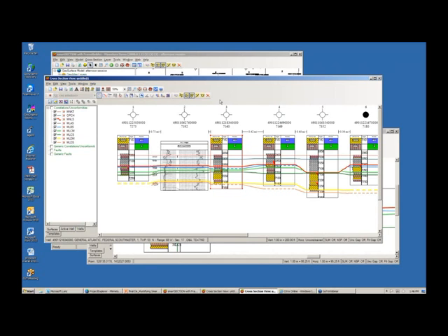And I just want to add a little to that, John, is that what you'll be converting is the list of wells in that cross-section. You will have to have an interpretation and a smartSECTION template built so that when you open up that list of wells, you can bring it in looking any way you wish. But if you had custom colors and all these fancy things in that old cross-section, those do not convert. You would need to redo that template here in smartSECTION. Yeah, it's about a 75 or 80% solution. I absolutely agree with that.